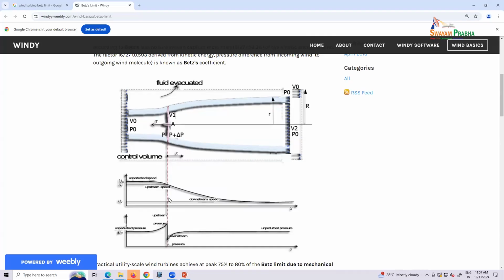If the wind here is totally blocked, the wind speed becomes 0, right? Then there's no energy getting out, right? If the wind speed has no decrease, then there's no efficiency either. So for this reason, the Betz limit is a scientific number you can get from the closed form solution, right? And you write the power as the speed going through here. You'll find if you reduce it by 1/3, you have the best efficiency.